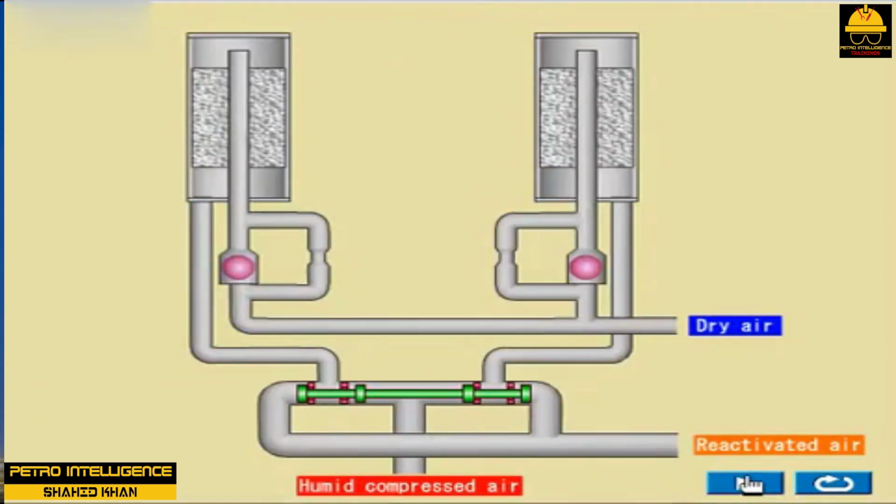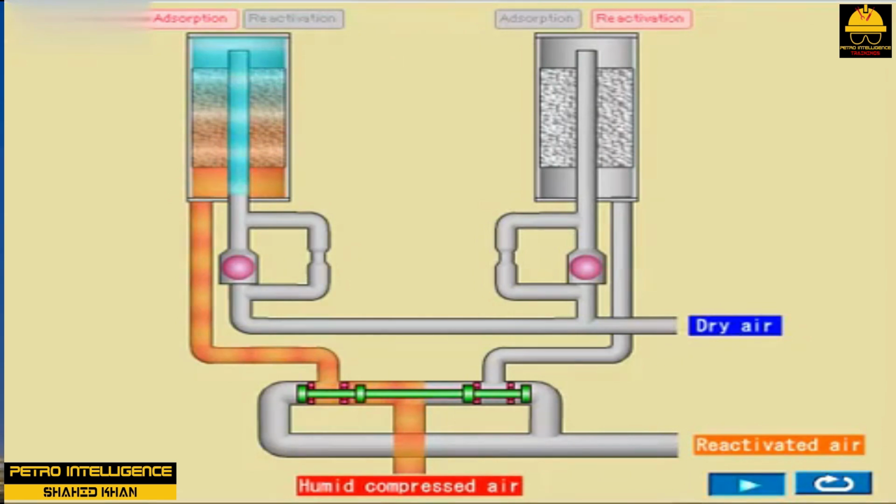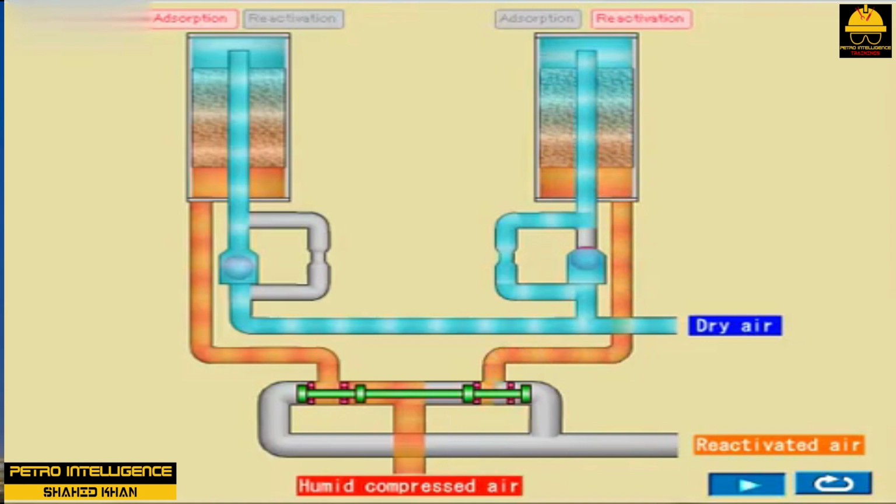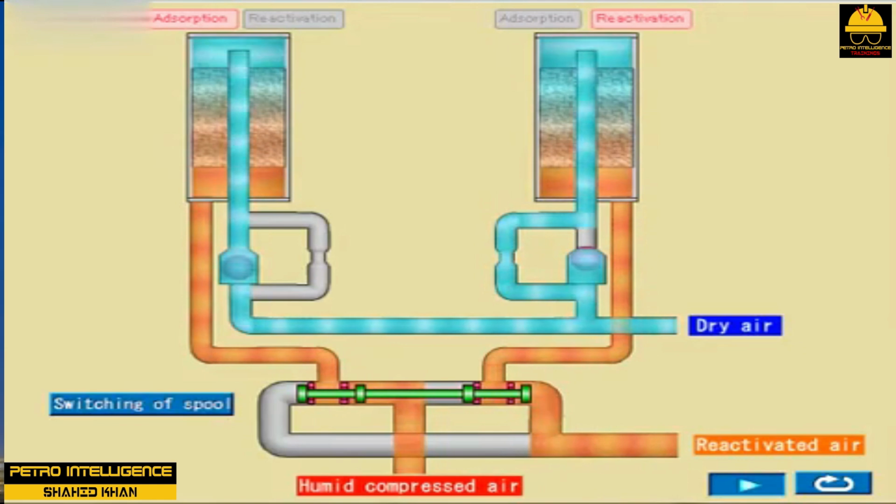Basically, the liquid on the surface is vaporized into the gas stream and carried away because of the difference in vapor pressure. The regeneration of the solids in a gas dryer can be considered a small-scale operation of drying the granular product from a chemical plant. In the case of a final product, the quantities are usually so large that special equipment is used to handle it, but the principle is the same. The moisture adhering to the solid is vaporized and carried away by a gas stream because the vapor pressure of the moisture on the solid is lower than that in the gas stream.